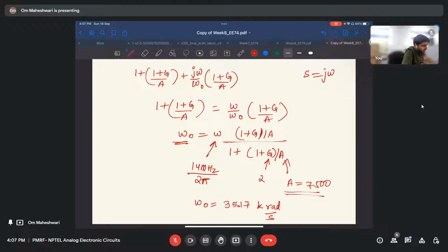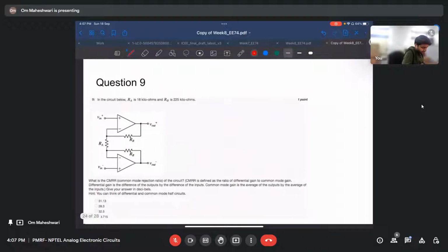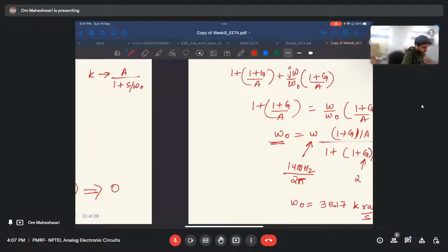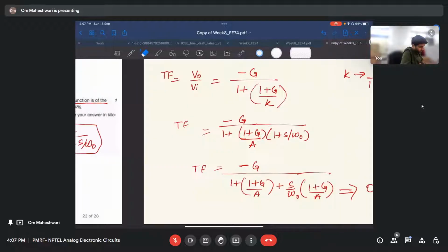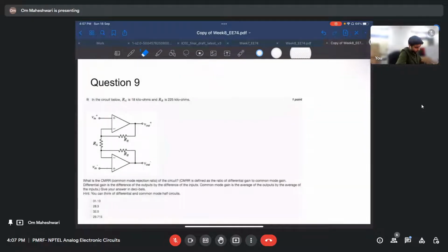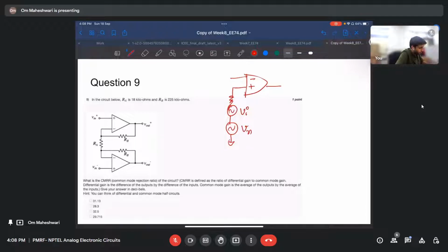Okay. So how do we characterize noise? An op-amp is simply an amplifier, right? So whatever the input. If you see, let's say this question, an op-amp is simply an amplifier. If noise is coming here, let's say you're applying some signal Vi, but you are getting some noise also. So it will amplify noise also: A times Vn plus Vi.